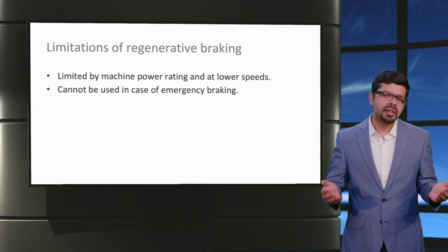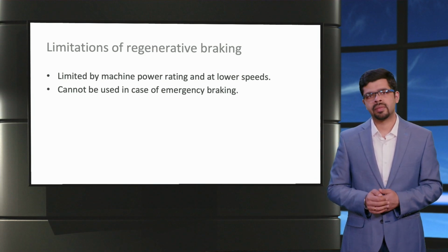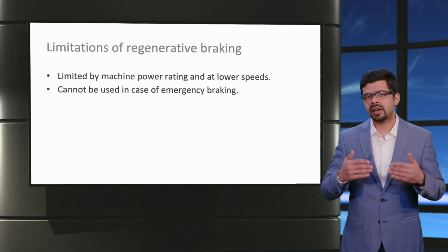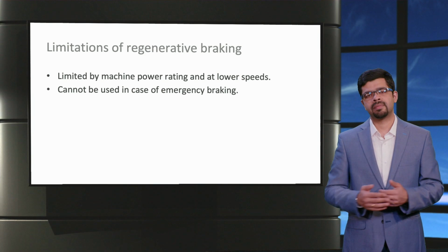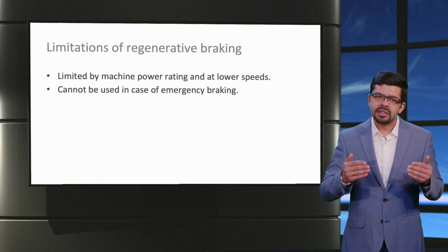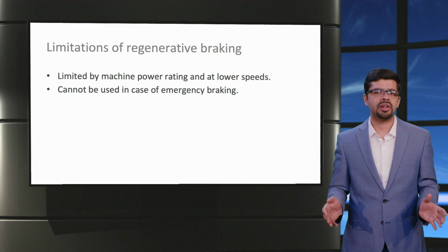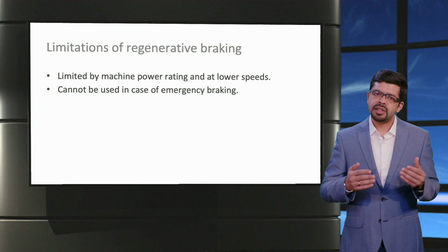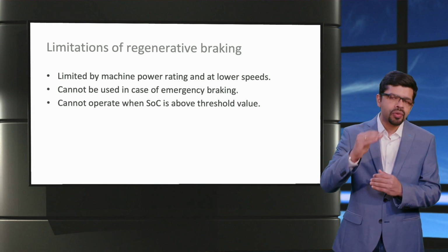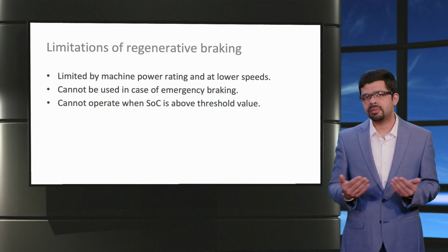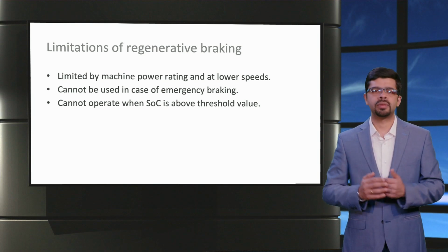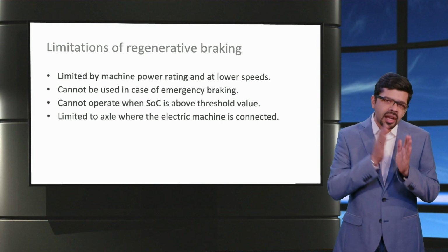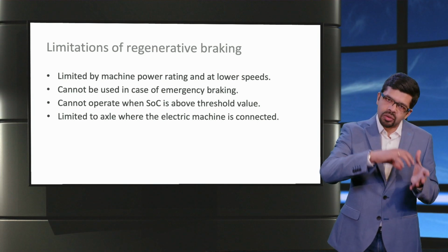Finally, let's look at the critical limitations of regenerative braking. Regenerative braking is limited by the power and speed range of the electric drivetrain, especially the electric machine. This means it cannot exclusively be used for all driving conditions and is always combined with mechanical braking. Thirdly, when the battery pack is almost full, additional charging via regenerative braking is limited or not possible. Finally, regenerative braking is limited only to that axle to which the electric machine is also connected.